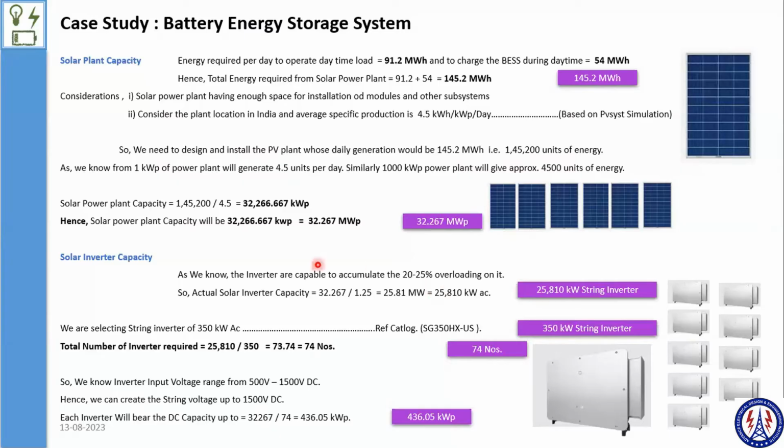The manufacturer is Sungrow, because I'm considering a combined solution from them. The source company is similar, so I can deal commercially on a viable solution for us. I consider 350 kilowatt, and technically it serves all my requirements. So the SG350HX model is what I considered as a string inverter.